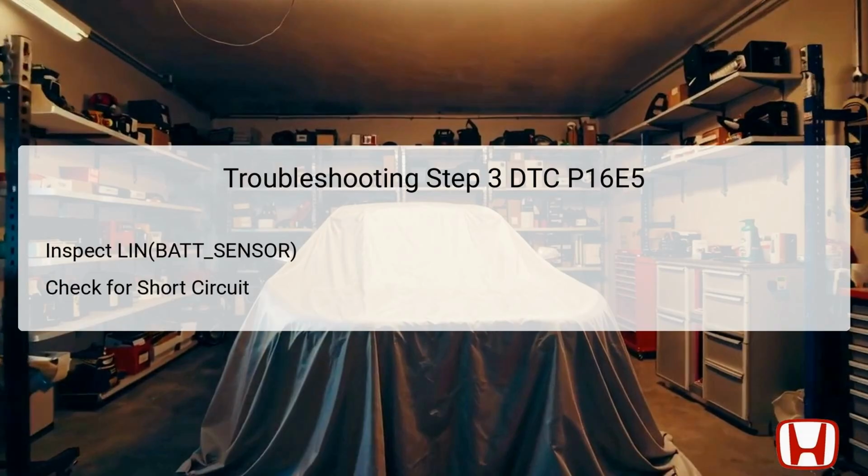This is critical since the LIN protocol facilitates communication between multiple components in the vehicle, including the PCM. If the inspection reveals that the circuit is shorted to ground or has open wires, it may affect the PCM's ability to receive signals properly. Consequently, it's important to ensure the resistance levels meet specified values, particularly that there's more than 1 megaohm resistance in case of a detected short. This step is pivotal in isolating the specific circuit issue to rectify the communication error effectively.